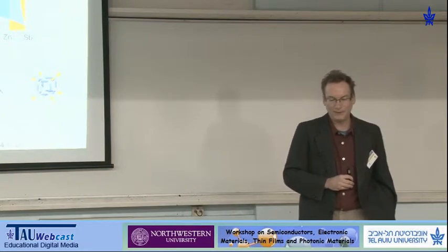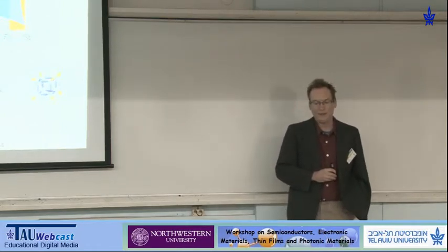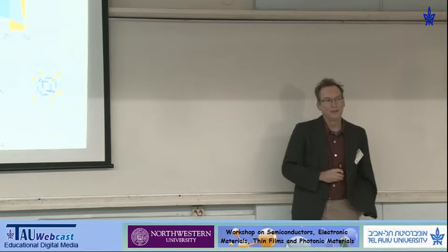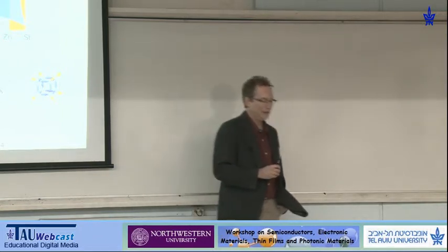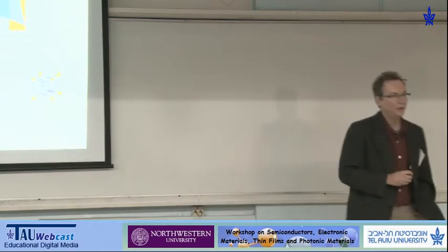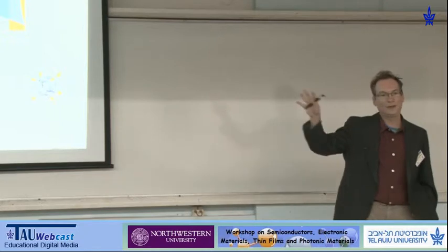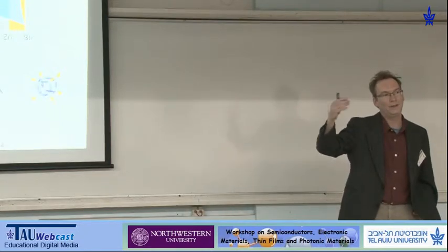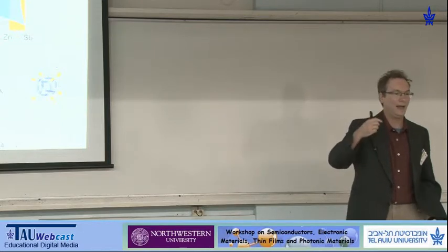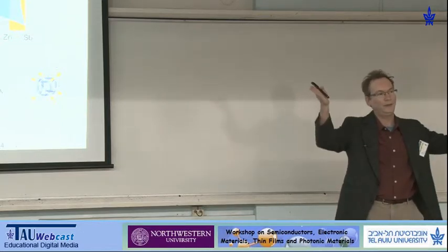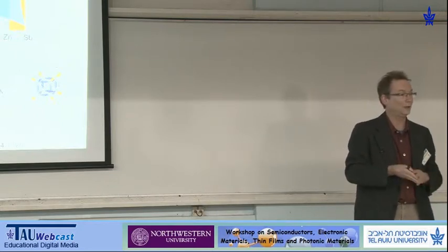The mechanical aspect, I don't know, but the temperature variation should lead to dopant precipitation. So we've seen this. None of these materials are thermodynamically stable, right? So at low temperature, they're all kinetically stabilized. The dopants have solubility that increases with temperature, and at low temperature, in most of our materials, the dopant isn't actually soluble anymore.